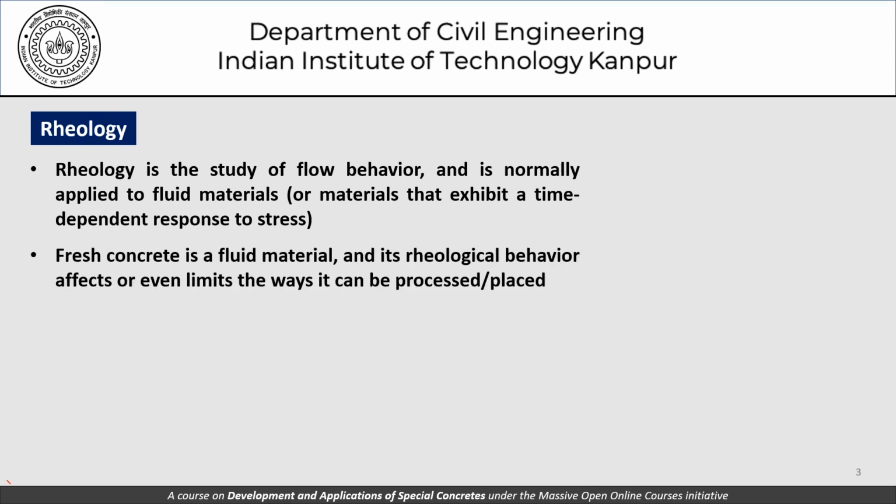Fresh concrete is a fluid material and its rheological behavior affects or even limits the ways it can be processed or placed. When we say it's a fluid material, of course, something like roller compacted concrete would be difficult to visualize as a fluid. Other concretes, whether they are self-compacting or not, do try to behave like fluids. But even with the stiffer concretes, we should understand that as we apply vibration to them, as we try to compact them, we do expect the concretes to move and deform. And this deformation is also a part of rheological studies. So that's what we need to understand a little bit about.